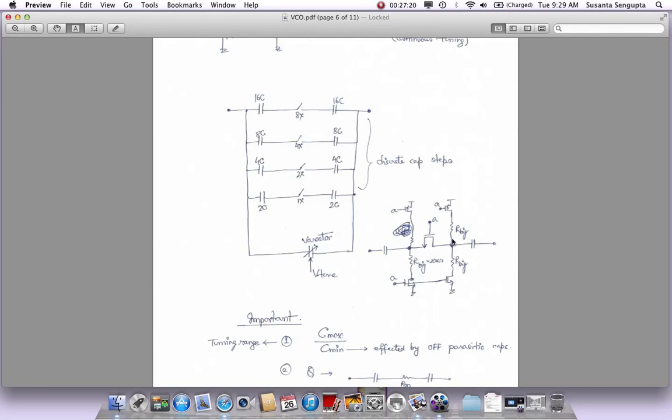When you go off, what you can also do similarly is, with big resistors, pull them up to VDD. So they go off more, because when they go off, we want this off resistance to be high. And not only that, when this cap is off, it will not look like just a resistor, it will also have parasitic caps with it. We want those parasitic caps to be smaller, and those caps will be smaller if the switch size was smaller, but unfortunately we wanted a bigger switch size when it's on, so there is a trade-off there. So in one state we want this MOS device to be bigger when it's on, but in the off state we want this MOS device to be smaller. Well, you just have to trade it off between those two and see which one works for your tuning range and also your Q when it's on. So this is how we can bias these points to pull them down or pull them up based on whether we are on or off.